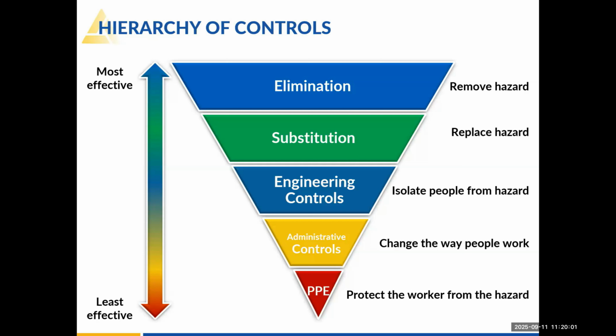And then once we've done the elimination part and the substitution, now we're getting into engineering controls, administrative controls, and PPE. And I've got some follow-on slides that go a little bit more in depth on that. But engineering is really isolating the people from the hazard, building barriers, keeping people away from the hazardous areas on a particular machine or a particular area in the facility.